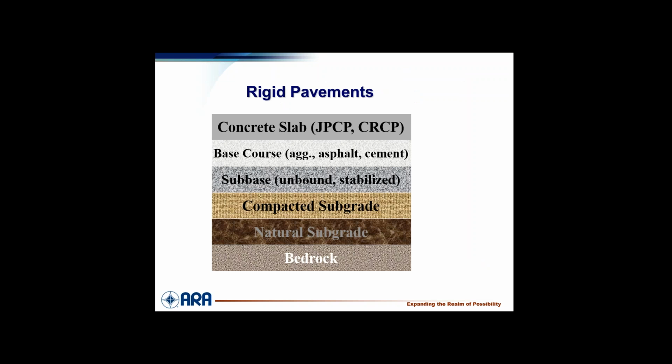On the concrete side, again, it's a layered system. And that was almost a new concept in concrete pavement design, because people thought, well, it's a slab, and then whatever is under there is under there. It's a K value. It's a spring constant. That isn't true. That is complete nonsense. It's a layered system. It's a composite beam. And so you have friction between these layers.